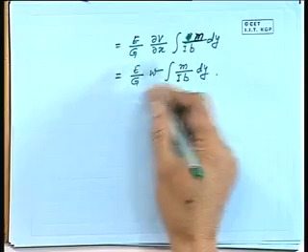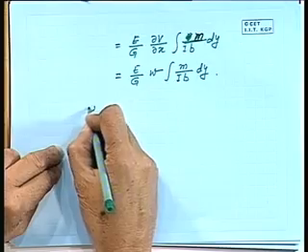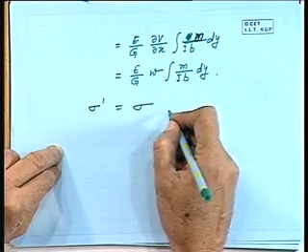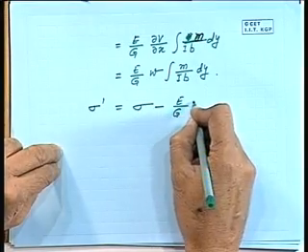Because when you are trying to pull it this way, there is a force tension here. So, tension means this upper side will go down like that, and in the lower one the stress is in this direction. So, if this stress is in this direction, then obviously this stress in the lower fiber is in the opposite direction. So, the net bending stress sigma dash will be the usual bending stress minus this quantity.